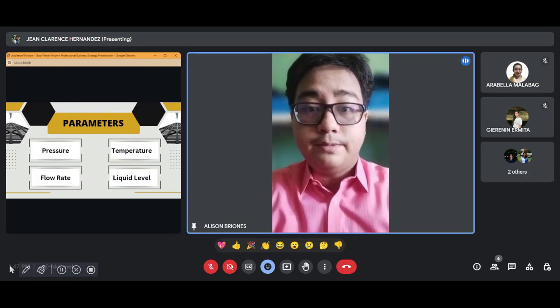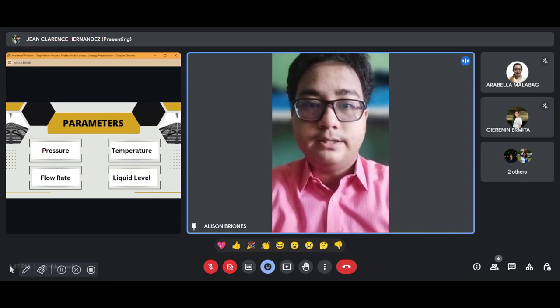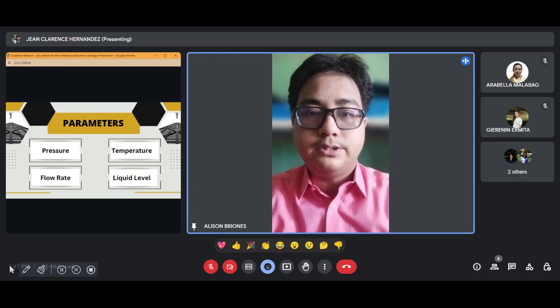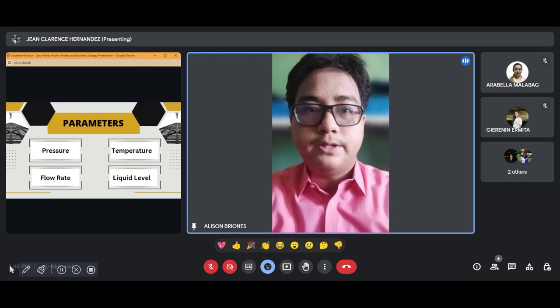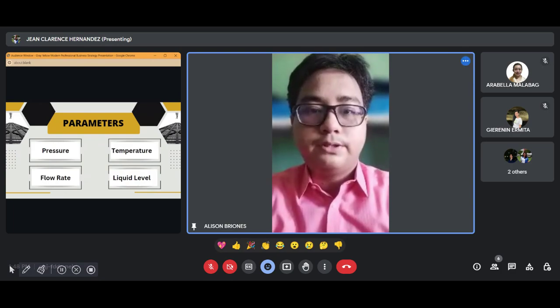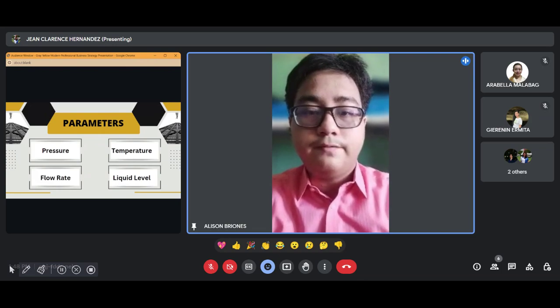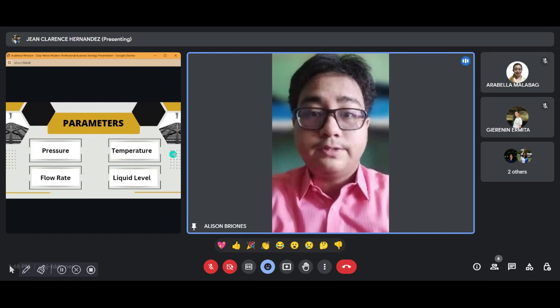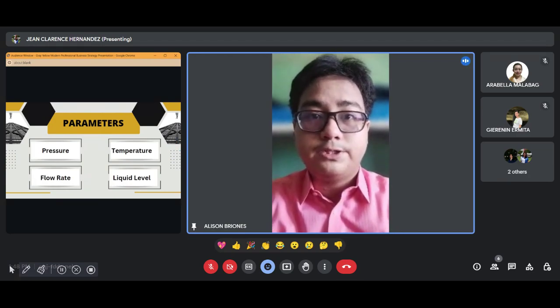First, pressure is a pivotal parameter in the process and is typically controlled at different points of the system to optimize conditions for glycol circulation, absorption, and regeneration. Pressure helps maintain the desired flow of wet natural gas and glycol within the contactor tower. It is crucial to have adequate pressure for ensuring effective gas and liquid interaction, thus promoting efficient water vapor absorption by the glycol.